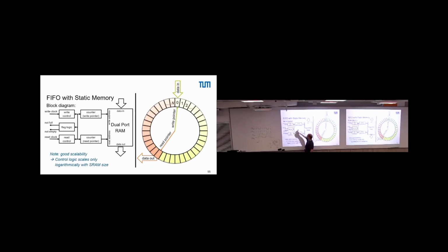There is a logic and a flip-flop that says, if data is written and this comparison holds, then trigger the flag. This flag is triggered by the write process, so it is not synchronous in the read domain. That is a point which is asynchronous.